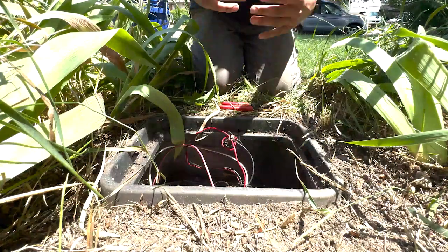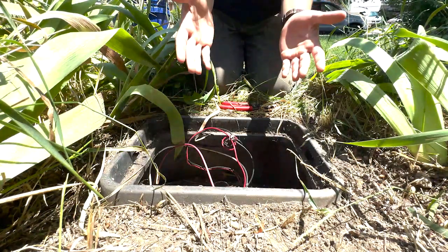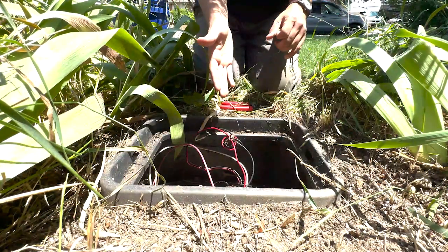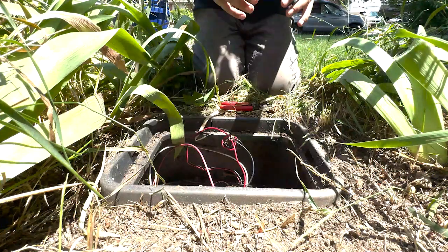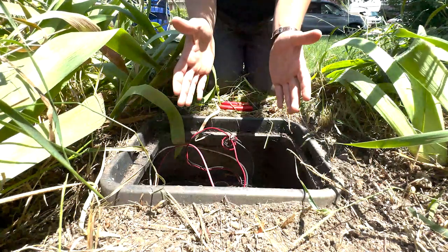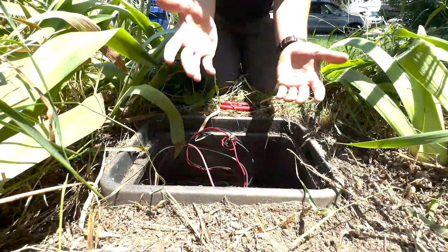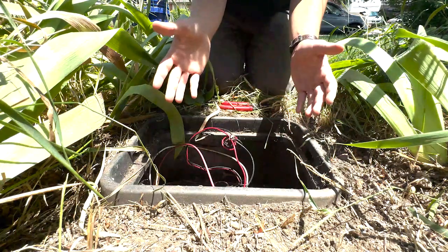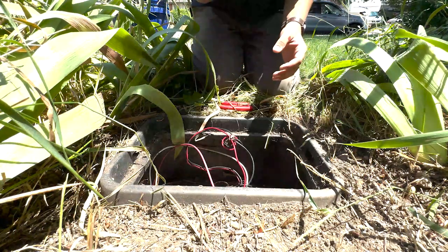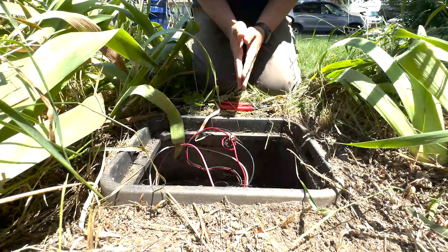If our wire loop does have this ability, then we can conclude that the problem in our flow loop is with our flow sensor. If our wire doesn't carry that flow data, we can conclude that we have a bad wire loop and there might be a cut or damaged wire somewhere between this flow sensor and our controller.